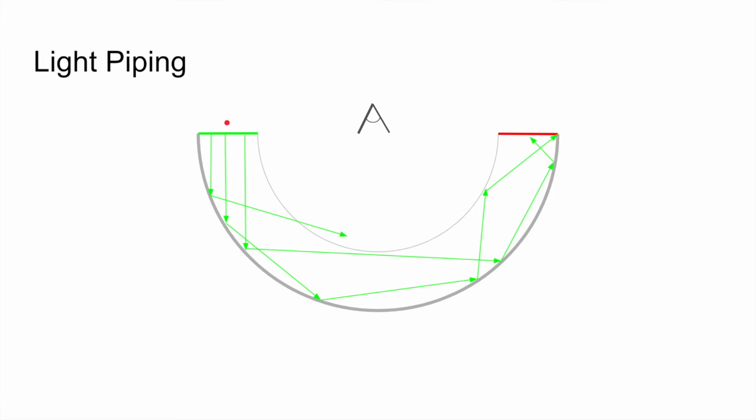The important principle behind this design is that we have this sensing surface with that silver dollar coating, so it will reflect in the direction we want. And because we're working with a clear plastic shell that's pretty thin, we can use the principles of total internal reflection to keep the light in. So what does that mean? If we look at this right here, when it hits the plastic surface, if its angle at the plastic-air boundary is less than some angle, it won't escape out of the plastic shell, but will be reflected back towards the sensing surface.